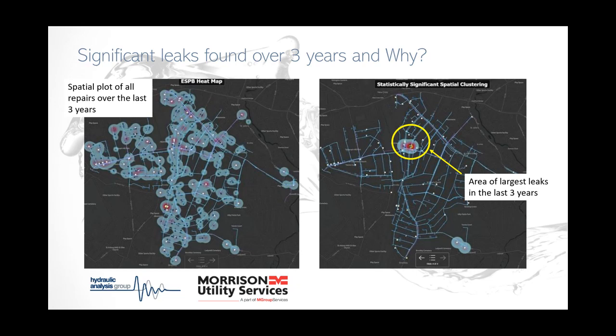Find and fix is great; it'll always have its place. But our idea is, if the water companies really want to tackle leakage properly, you need to stop these leaks and bursts happening. And pressure transients are without doubt the main cause of leaks and bursts. Yes, there's other things like other services interacting with the pipes. There's traffic, ground loading, but pressure transients are one of the key factors, if not the largest factor associated with leakage.